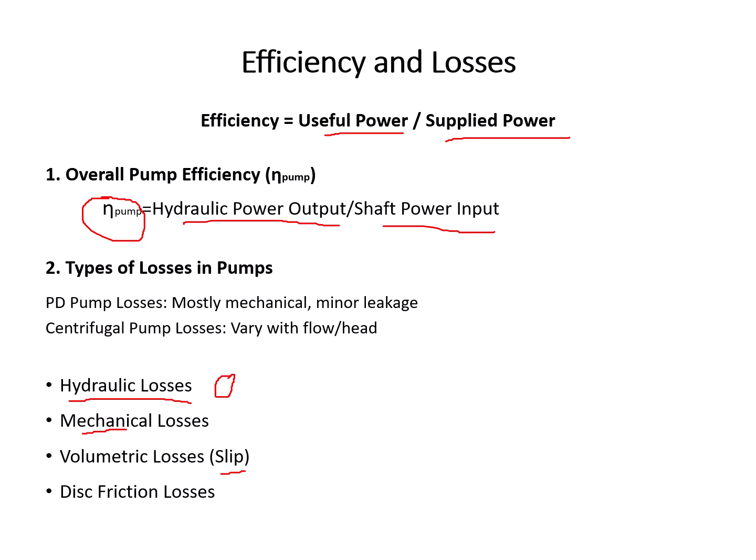Disc friction losses happen specifically in centrifugal pumps, as the rotating impeller causes drag of the fluid between the impeller and the pump casing. That causes the disc friction losses, which waste energy in stirring the fluid that does not contribute to output.